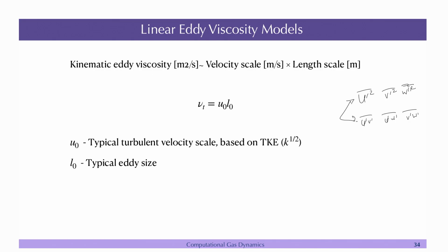right. Just like you have the dynamical equation for the density, which is the continuity equation in compressible flow, or in the momentum equations you have dynamical equations for u, v, w, the 3 velocities, in incompressible or compressible flow. Similarly, you have to have 6 different equations for this. There will be an unsteady term, a convection term, dissipation of these stresses, production of these stresses, and so on and so forth. Right. So, you want 6 more dynamical equations apart from the Navier-Stokes equations that we have. You solve these equations, get these quantities, and put them into the Navier-Stokes equations, the RANS equations. That approach is called the Reynolds stress model.